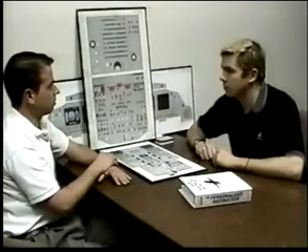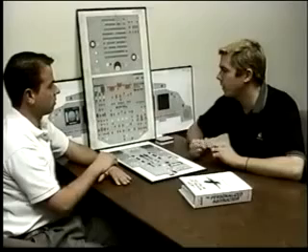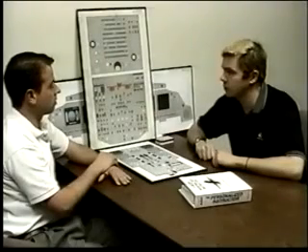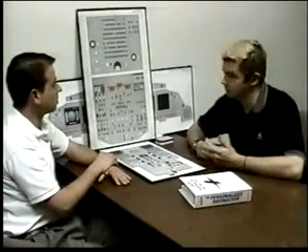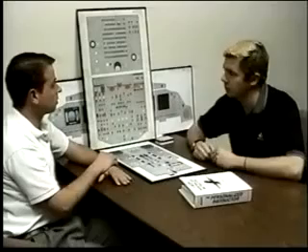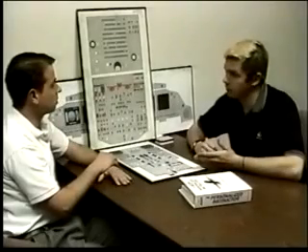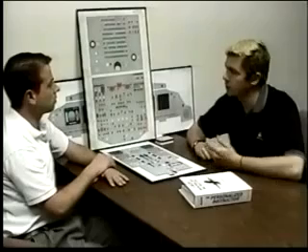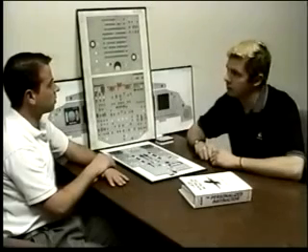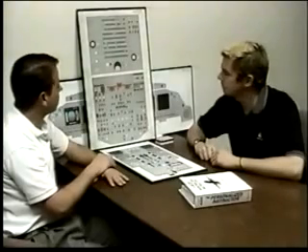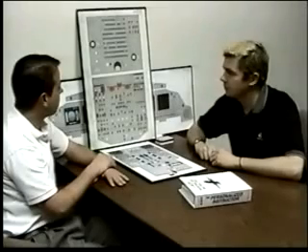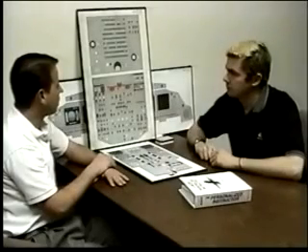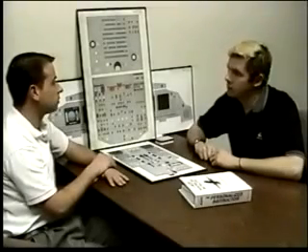It's changed to 3,300 pounds. Another one we have out there is the minimum desired landing fuel, which is 1,600 pounds, broken down to 400 for the landing or at touchdown, 800 for the go-around, and 400 for the fuel gauge error. That 3,300 fuel imbalance, is that all phases of flight? No, that's only for takeoff and landing.